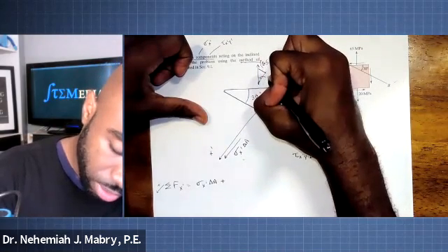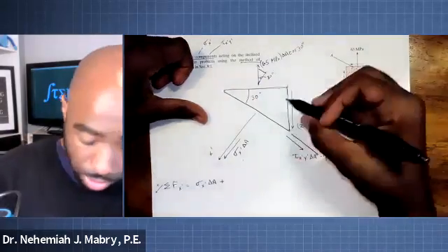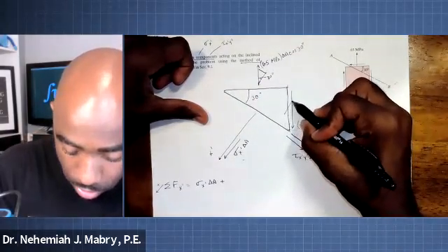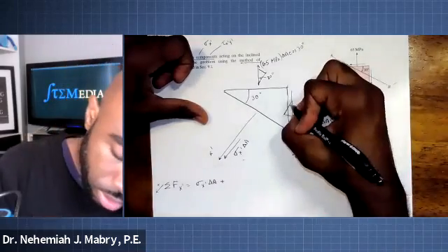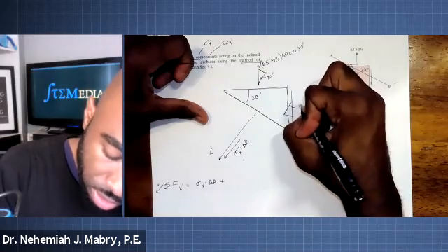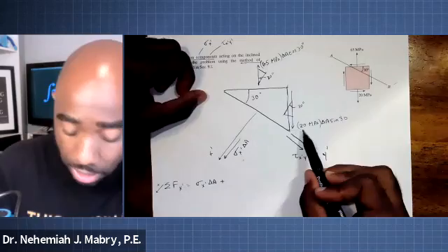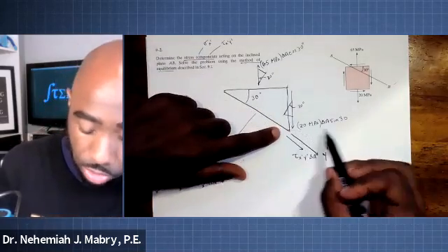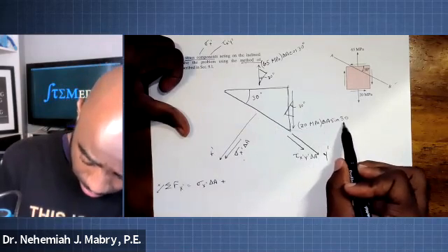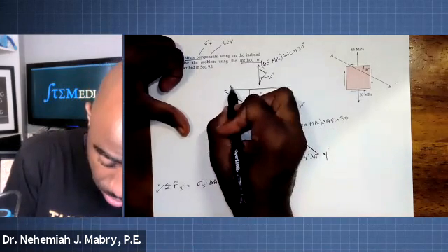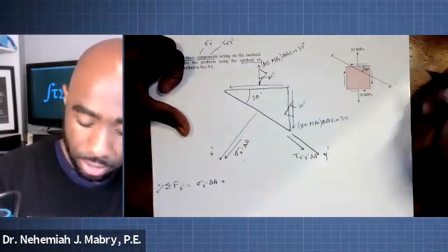And know that that's 30 degrees. We would need to know that this angle here is also 30 degrees. And I realized I left off another force, another shear force, or I could draw it another way. Because just like we have the 20 MPa times delta A sine 30, we need to make sure we show that shear force here for that line there.